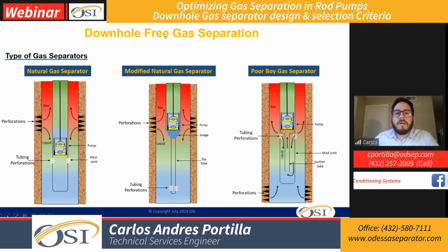Basically, we need to understand here that we have two velocities interacting. One will be the velocity of the liquid, which is the surface liquid velocity, and the other one will be the slip velocity of the gas bubble. To have gas separation, the slip velocity of the gas bubble will need to be higher than the liquid velocity. And here we have the perforations above the pump intake, right?